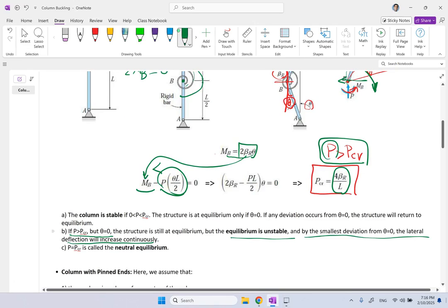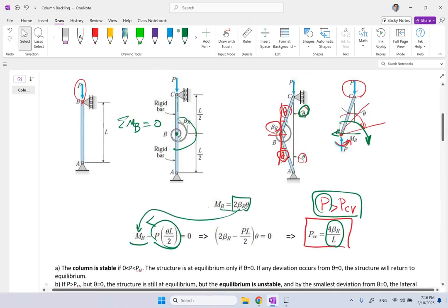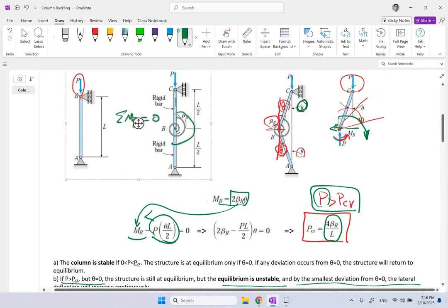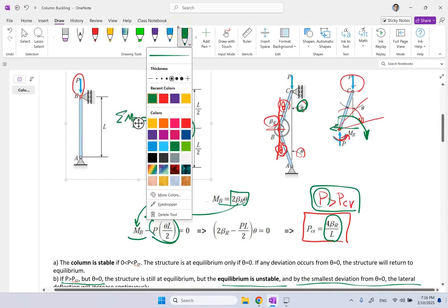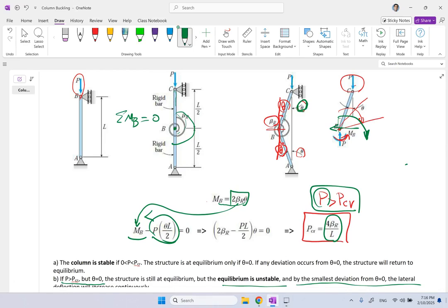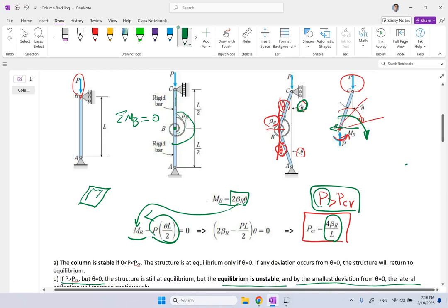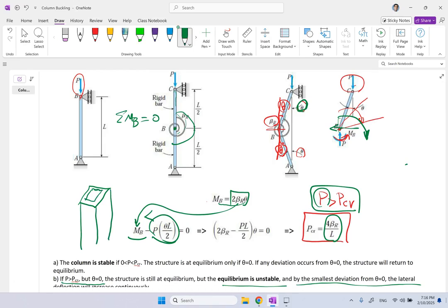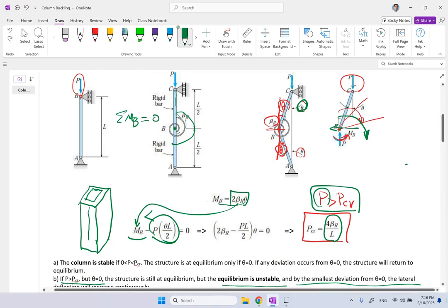And you might say, well, can't we always make sure that the load P is along the column? Well, the matter of fact is no. Because if you look at many of the columns in real life, let's say, for instance, you have a C-beam or just a simple pocket like this, a cross section. So this is a column under a building or anything. And this is the line that your P should be perfectly along.